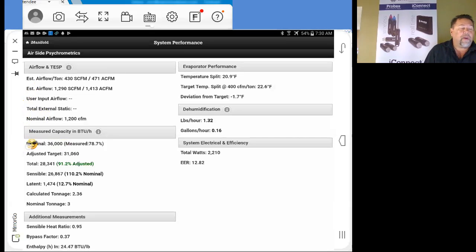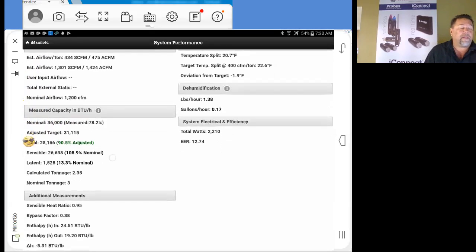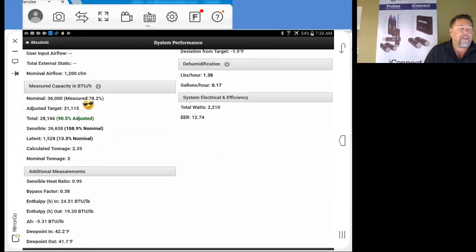So you've got your nominal BTUs measured. What we're doing here, you're measuring out at 79.2%. Our adjusted target for the conditions is 31,115. Total BTUs that we're making right now, 28,938. 91.3% or 92.5% of adjusted target. So we're acceptable. It's not running great. Like I said, this system is just kind of a morphed up system, no real ductwork and things like that.